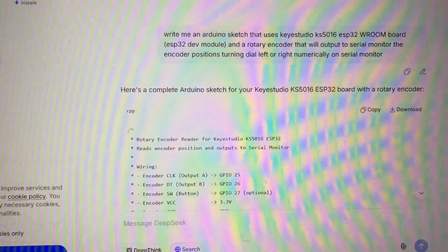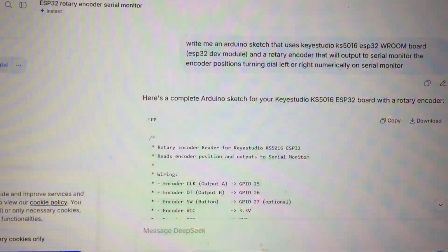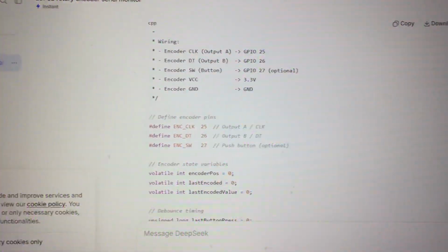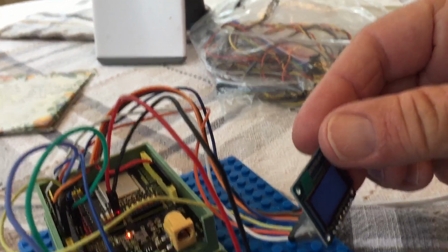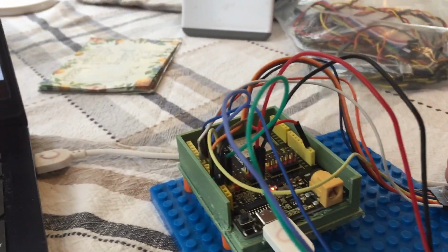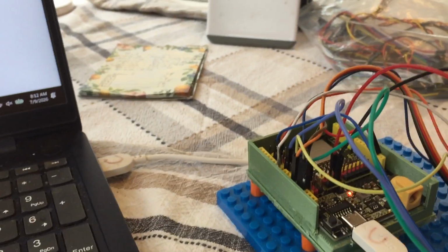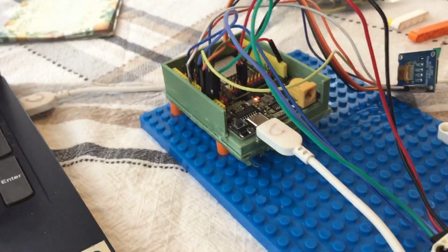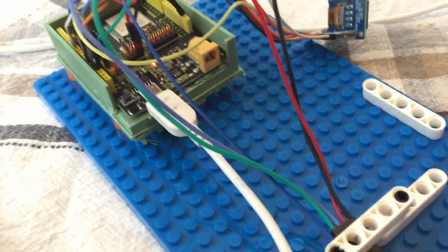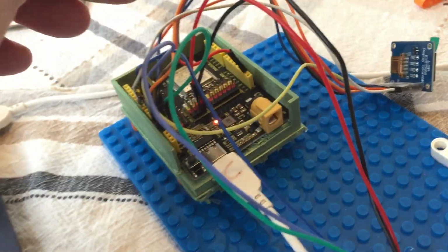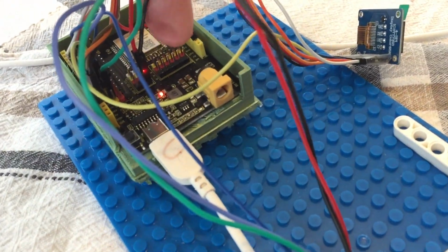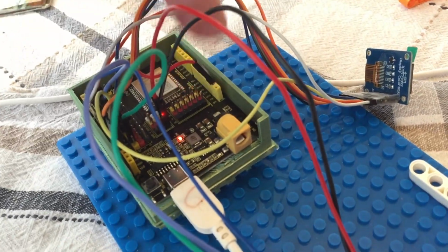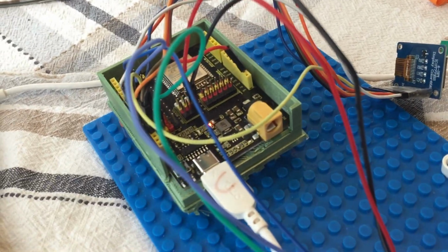and I changed those numbers because I already had some of them taken for this color monitor, which we've been using. But that's all right because I've got extra pins on this board that I could use. It calls for voltage and ground. On this board, I find that I can use any of these pins, whether I use the digital part or not.